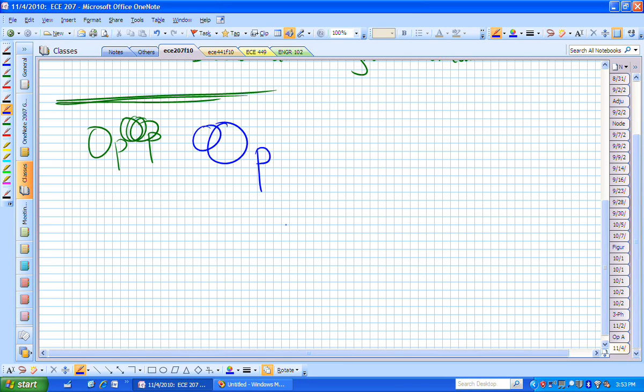Let's now apply KCL at the inverting node. If I do that, I'm concerned with the algebraic sum of the currents at that node, which has to sum to 0. Or I could say I1 seems to be coming into that node, and I sub x as well as I sub 2 are leaving.